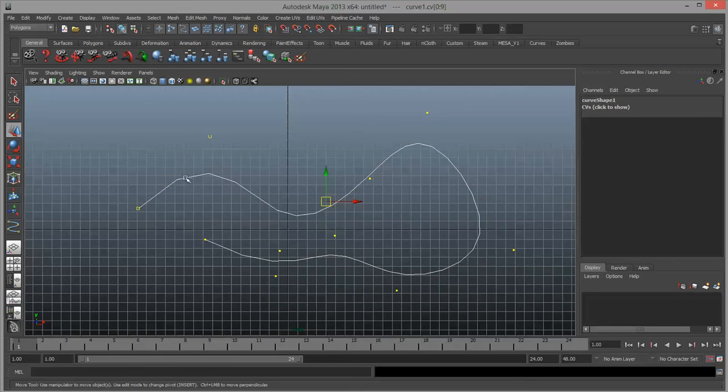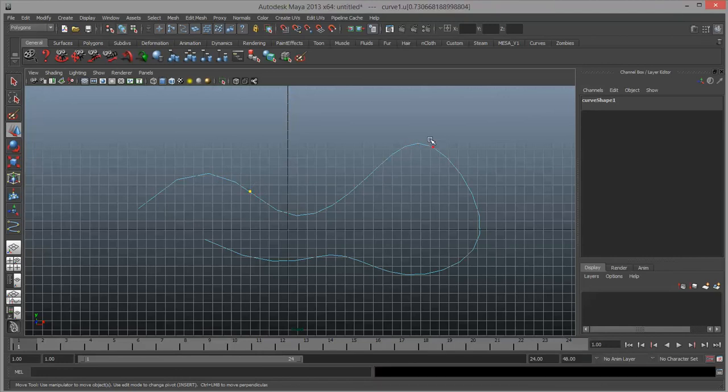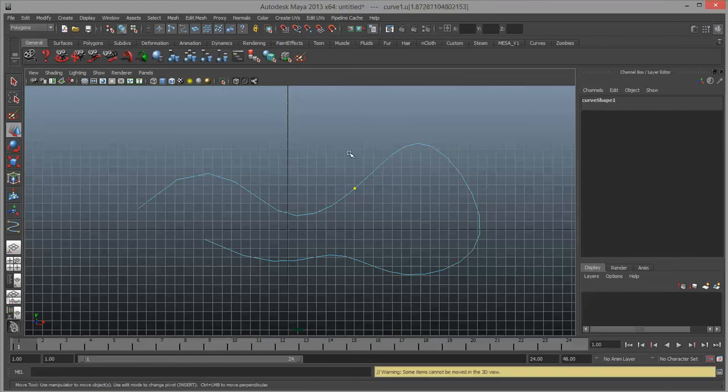Curve Point will allow you to grab a point on the actual curve itself, but it doesn't actually do anything. It will allow you to insert additional detail in certain parts of the curve, but that's it. And eventually it will give you more control vertexes. So here I'm left-clicking and dragging. You can see this little red dot as I drag and then yellow when I let go. If I want to add more than one point, I can hold down Shift.